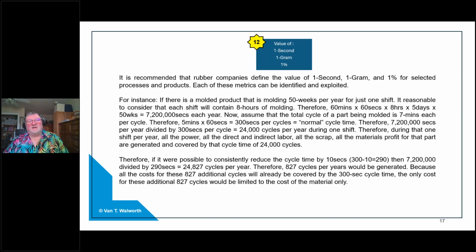I go into clients many times about their process and they say, oh no, there's no way that we can shorten the cure time. There's no way we can raise the temperature. There's no way that we can make the cycle time shorter, because if there was, we'd have already done it. I get that a lot. And yet they won't have actually looked at how slow the press is opening and how slow the press is closing and clamping. They won't necessarily look at how slow their injection time is and the things that they can do to mitigate that or to shorten it. Even just 1 second, there's a lot that can be done.